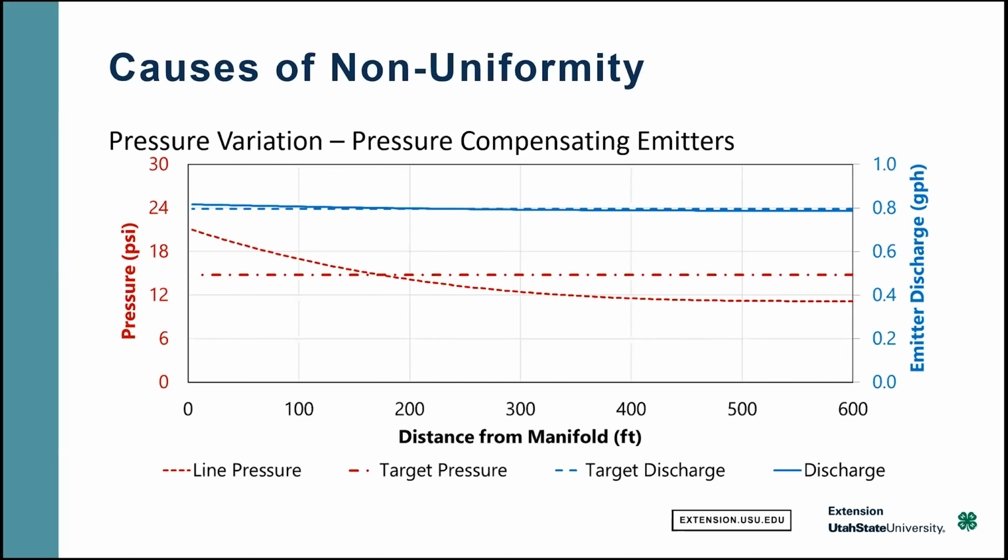In addition to having maybe a little tortuous path like I showed, they might have a membrane, like a little silicone membrane or something that sits against the valve and compresses with pressure or releases when there's less pressure, that causes the emitter to have more uniform characteristics over a large pressure range.